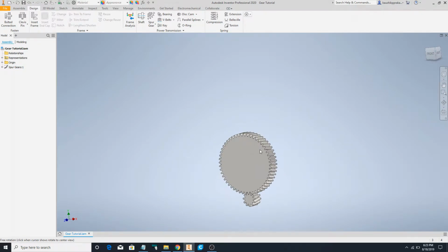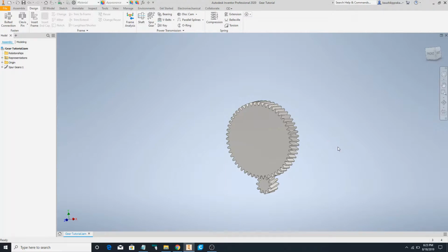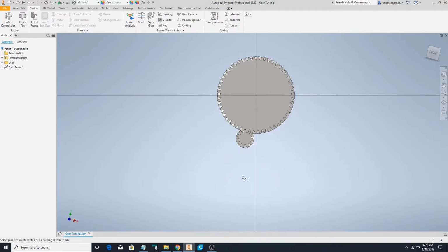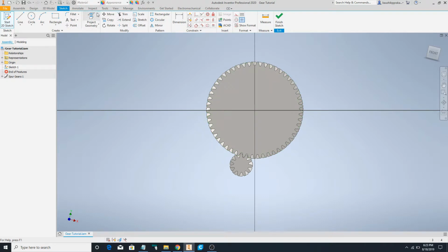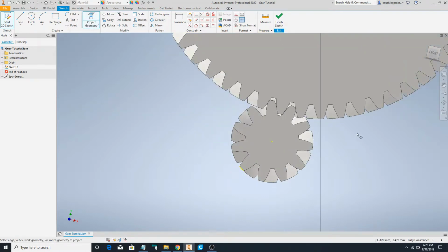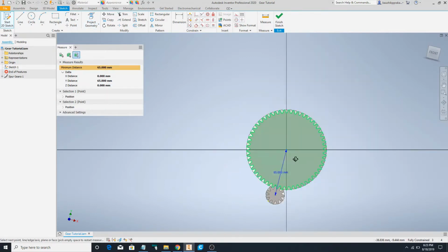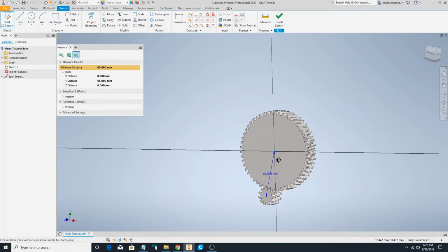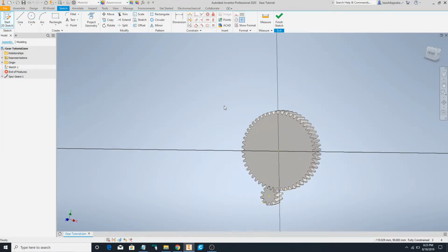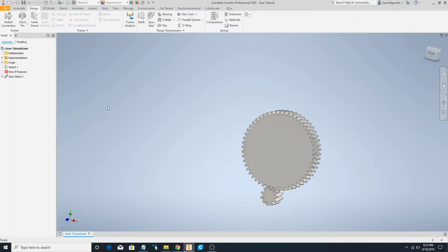And now if you're wondering what center distance is, because I know when I first started out I didn't actually know what center distance was, a quick Google search will give it to you, but we can also see Inventor show that to us. So the center distance is exactly what it sounds like. It's the distance between the centers of the gears. And changing that parameter allows you to implement the gears in a variety of scenarios depending on what application you have. For my robot arm, my center distance is usually dictated by how much space I have and clearance, but you can change it depending on where you're using it.